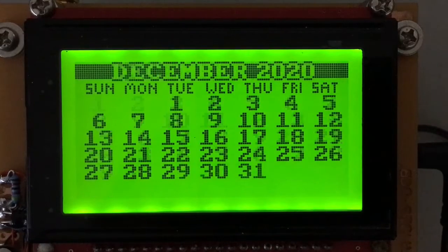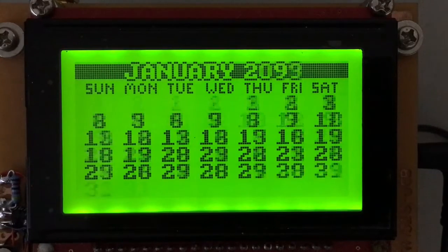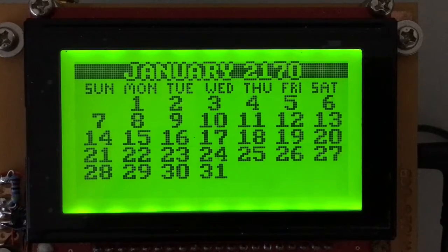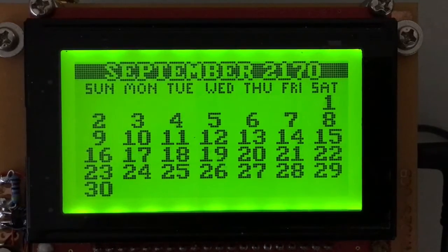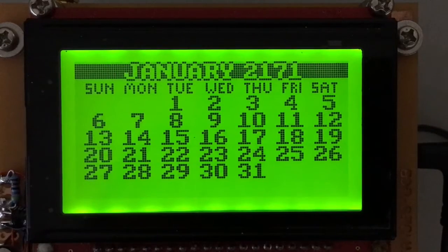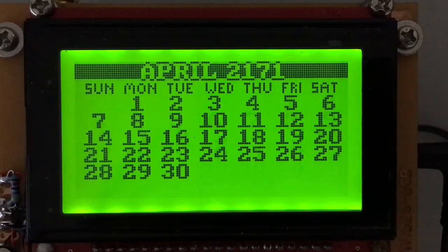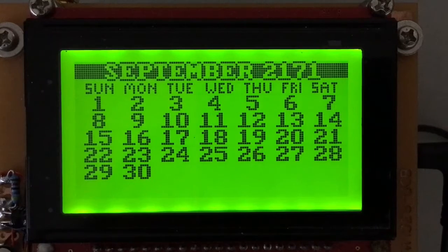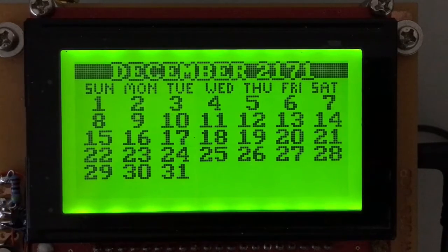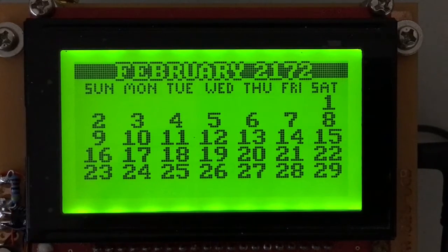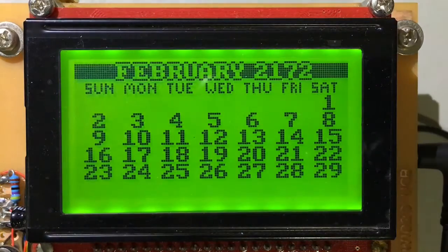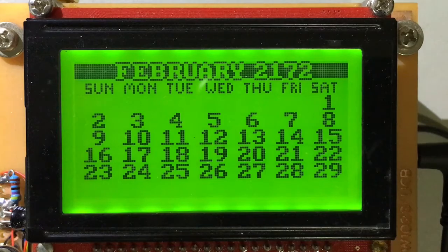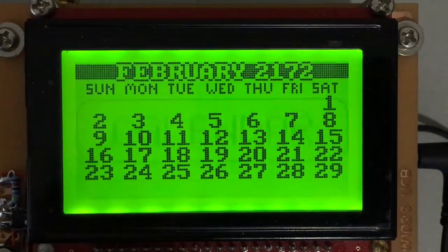Now, if you've seen the previous videos with the previous font, this is the first one with the new one. Yeah, I'm sure you'll agree it was all worth it. I've cheated a little bit here and I'm only using the uppercase characters, digits and some symbols. For the first font though, the HD44780 font, every printable ASCII character is defined, so that includes lowercase and all symbols defined on the ASCII table. It so happens though that there's no case where any of this software will ever print lowercase characters.